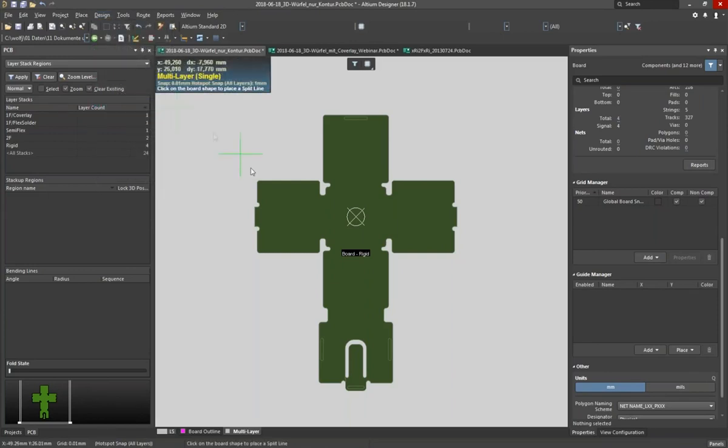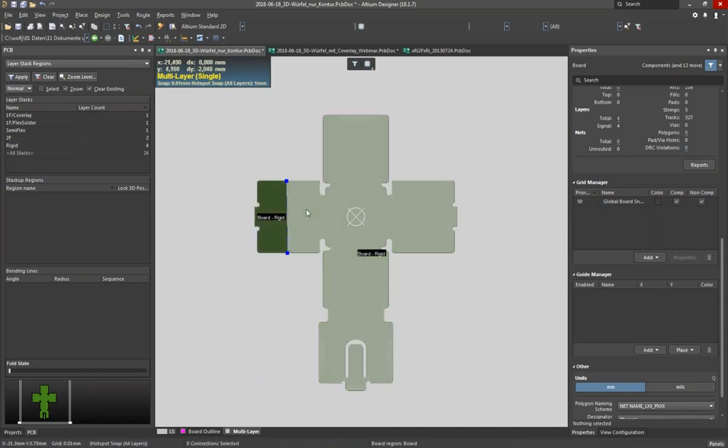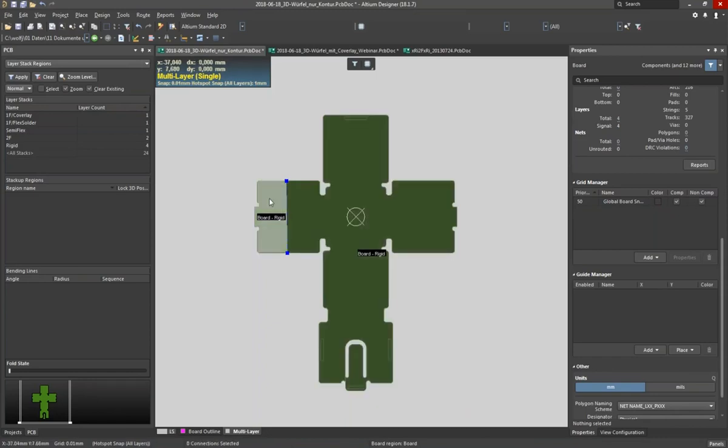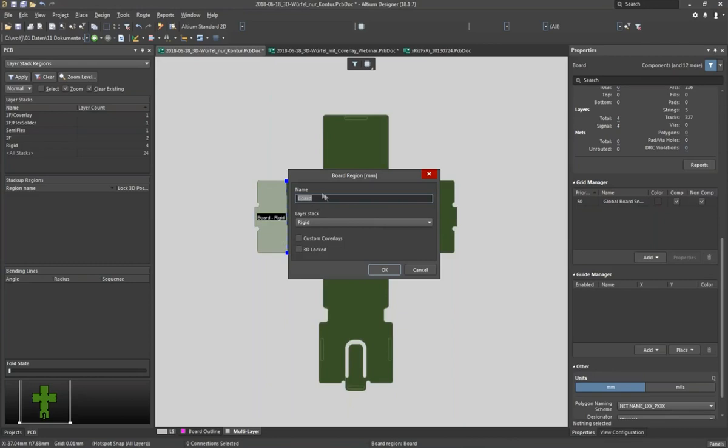Additionally, as I have just shown in the first section, for all those 4 flex areas, we have the flex bottom activated on the right side. So for the 2F and both 1Fs, we have activated the flex. Plus, additionally, we have the semi-flex defined as a flex as well. Okay, so layer stack, everything is fine. So let's go back to the board planning mode.